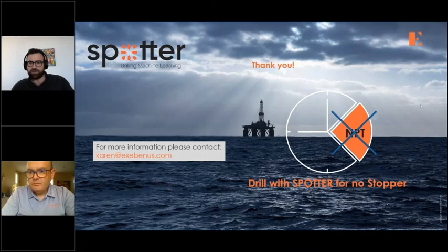And the final question we have here is, is the only required data source the EDR through WITSML? So yeah, that's correct. We typically use WITSML, but like I say, it's very standard surface parameters from the EDR for feeding to the software. All right, I think that's all of the questions I can see, at least in the interface here. So what is the minimum data frequency required? 1 second data is perfect. 5 seconds data is great. 10 seconds is something we can manage, but there can be some uncertainties.